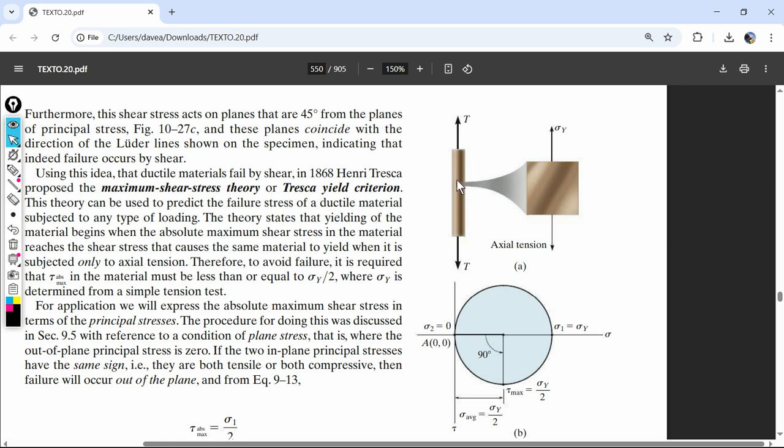And if we take this square, we're going to have compression this way, tension this way. But there's no normal stress in this direction, the x direction. So our principal stress is this. And when we rotate this, these get closer together. So this is the max, because this one doesn't go negative when you rotate it. You know what I mean? It might go negative. If this is a big positive number, there's a rotation where this might become a big negative number.